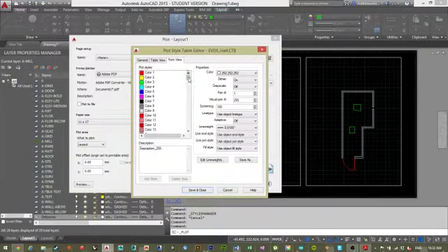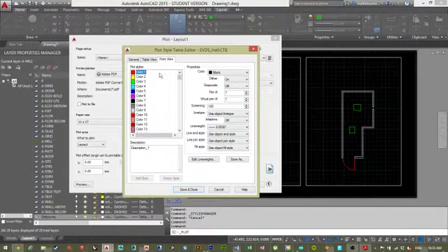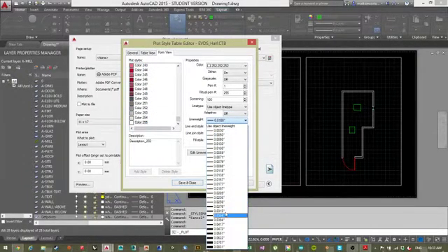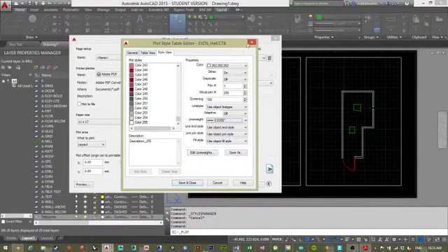So you could actually set, if you wanted to, 250 different line types, but that's overkill a bit. So that's why it's been set up to only use these first main colors that are separate in that color selector. So 1 through 7, and then white. So if you did want to print out your walls thicker, you could just come in here and change this to a thicker line weight.